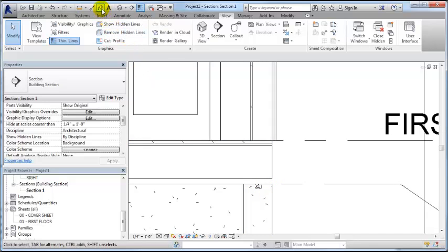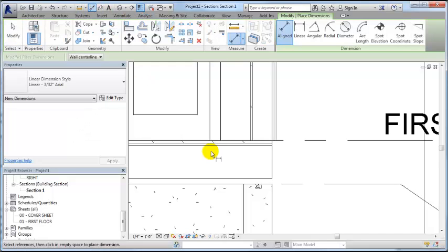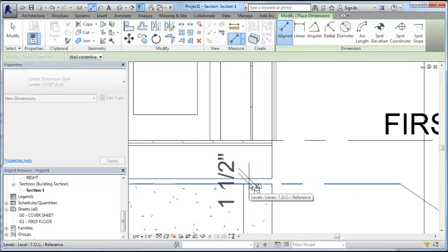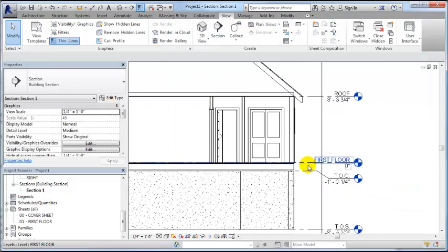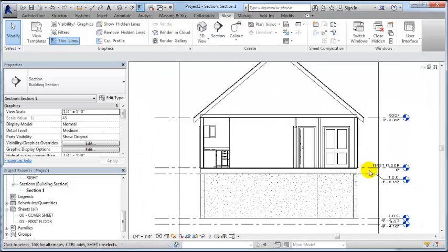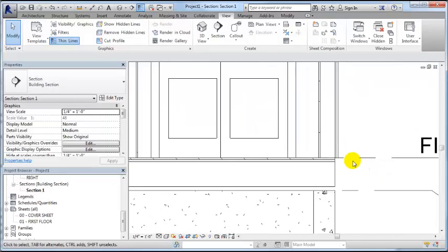Let's just check it. If I use this quick align dimension tool, I can click on the bottom of the floor and the top of the wall, and I get exactly 1.5 inches. That matches our mud sill depth, so I know that that's correct. Now a little later on in these videos, when I start talking about customizing, we are going to extend these two layers here outside down to the top of concrete, and then that will cover that face, and then we'll be creating a swept profile for the top of the wall that will create that mud sill.